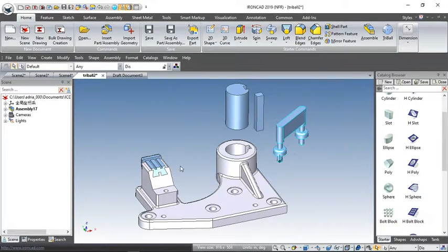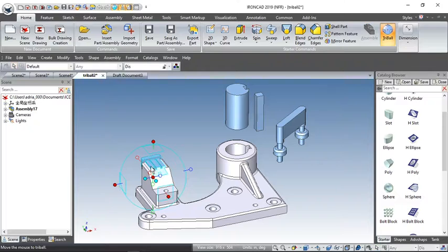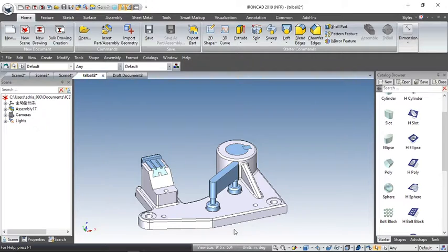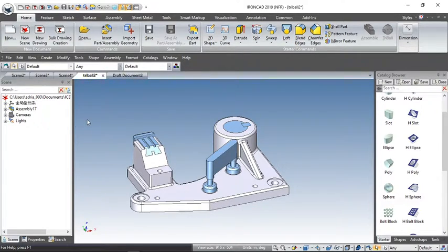So that's that, and we come to the final component here. We double click on that one, press F10, and simply left mouse drag the outer handle and move it up away from the part. So there we have our exploded assembly arrangement. In fact, I'm just going to bring that one down a little bit, keep it clean and tidy. So there we are. That's basically our assembly, including the configuration views that we might want to use in association with this drawing.